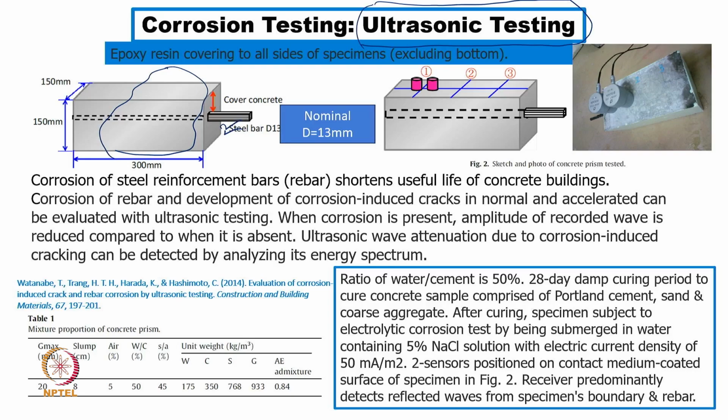If the chloride ingresses to the steel surface, there will be corrosion of the surface. And if there is corrosion of the surface, quite possibly the dimension, as I mentioned here, D3, the 13 mm can grow to D15, can grow to D20, and there will be an expansion of the surface.